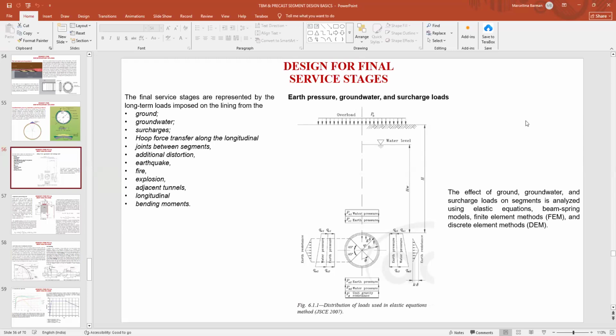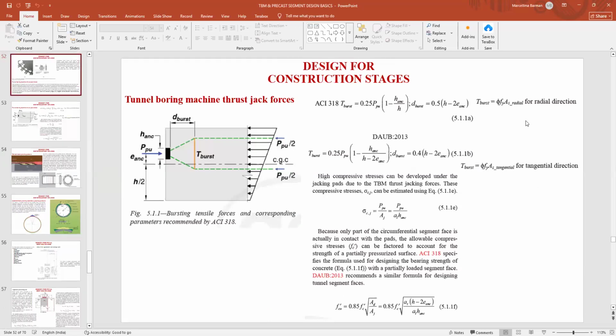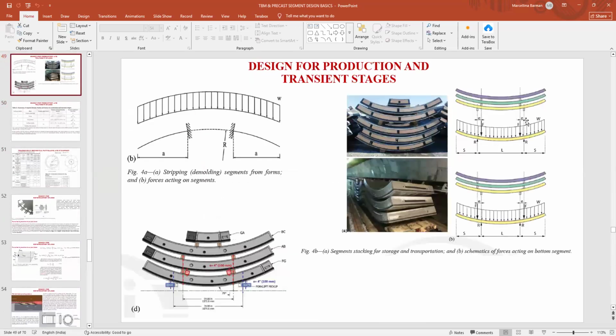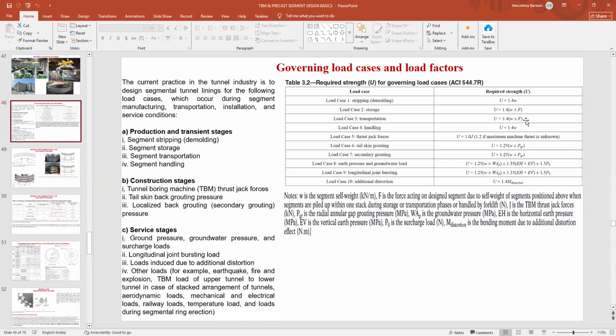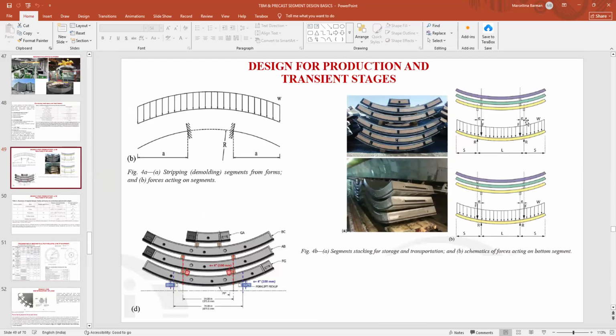Sir, because then there is ground settlement. Suppose the TBM crosses a normal area with a G plus 5 building, and the TBM crosses a G plus 50 building area. What will be the governing factor for TBM operation in that area? It depends on the ground cover also, what amount of ground cover I am getting there. So you are saying face pressure? Not face pressure. It is basically the ground cover.